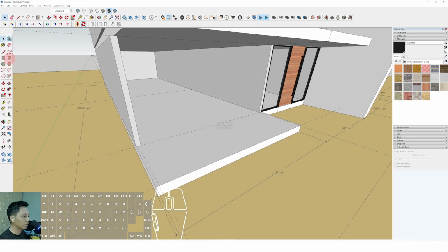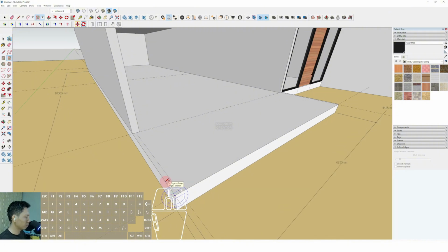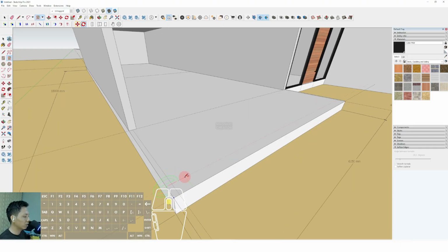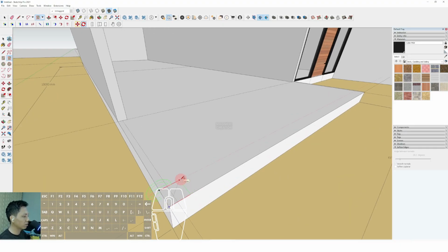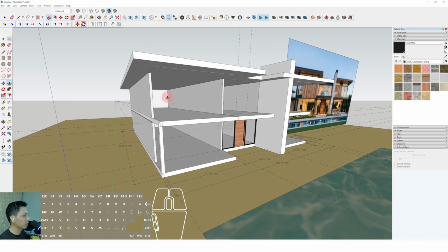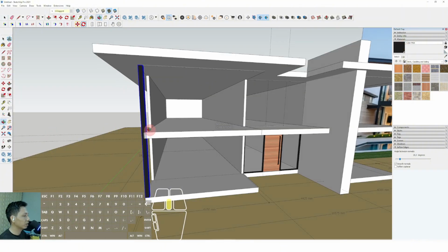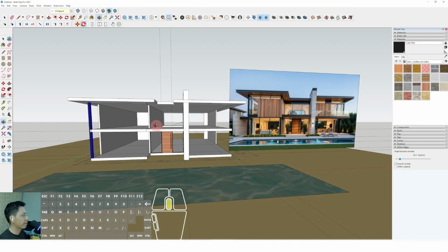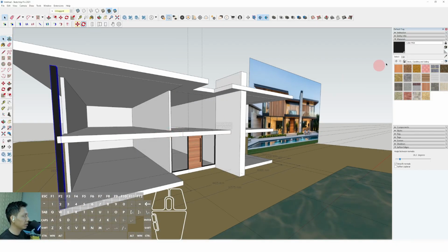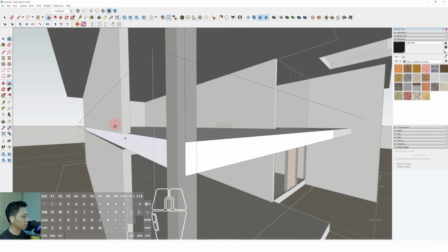Okay, we can select the rotate rectangle and click from this corner, and we can type 200 millimeter, enter, and 200 millimeter. Okay, we can click the surface and push it until the upper position like this, and we can triple click, right click, make group, and assign the color materials like this. It would be better if we assign the materials, but we have to fix it first.